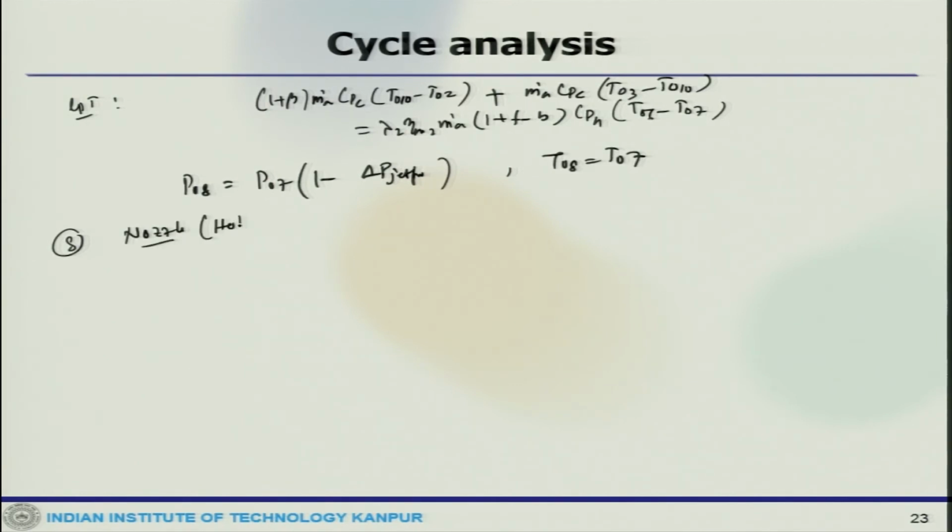This is the hot nozzle, let us say. Here the exhaust velocities of the hot gases from the turbine nozzles are obtained. After that we again have to check whether it is choked or not. So typically we will see Pc = 1 / (1 - (1/eta_n)((gamma_H - 1)/(gamma_H + 1))) ^ (gamma_H/(gamma_H - 1)).